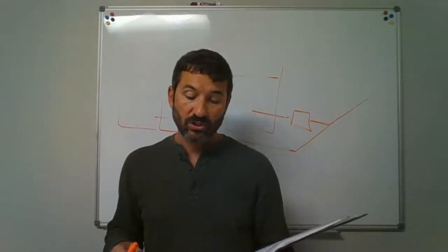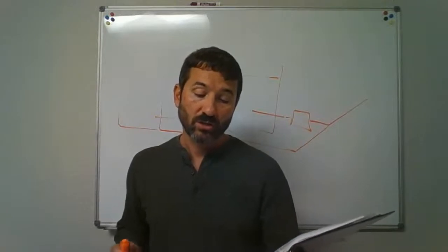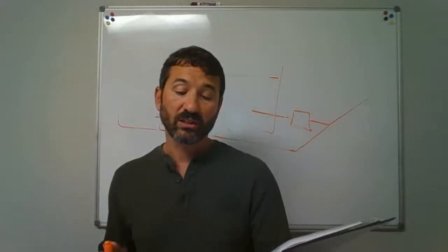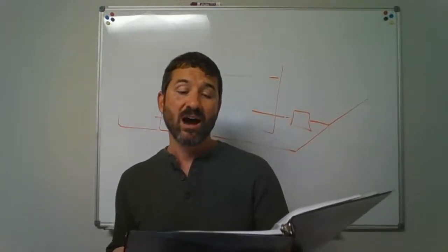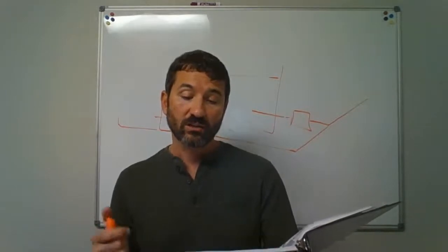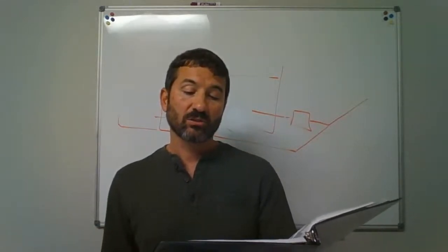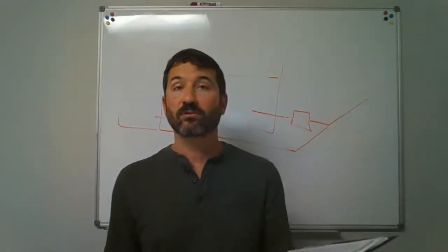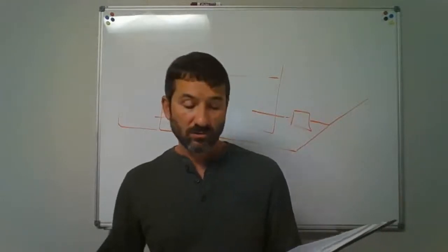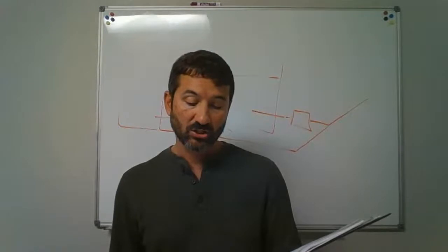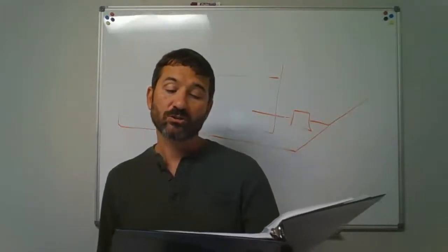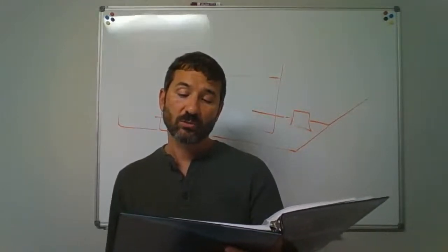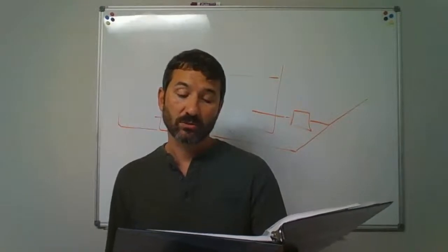Clothes washer discharge interceptors. Clothes washers shall discharge through an interceptor that is provided with a wire basket or similar device, removable for cleaning, that prevents passage into the drainage system of solids a half inch or larger in size, strings, rags, buttons, and other materials detrimental to the public sewage system. The exception is clothes washers in individual dwelling units. So if you've got your own clothes washer at the house, you don't have to have that. A single clothes washer designed for use in individual dwelling units and installed in a location other than an individual dwelling unit shall not be required to discharge through an interceptor.